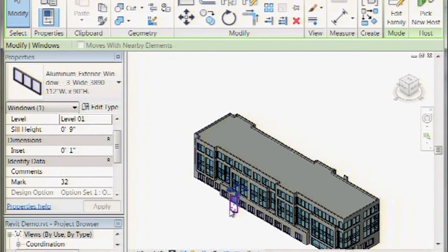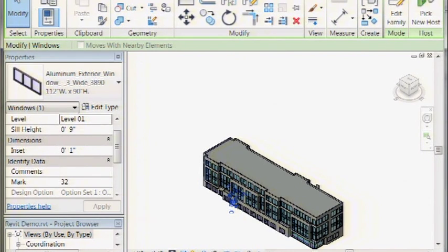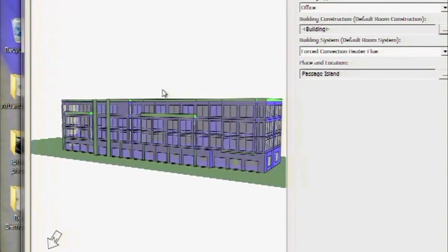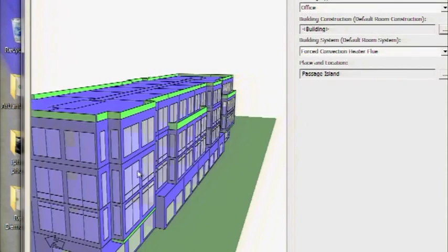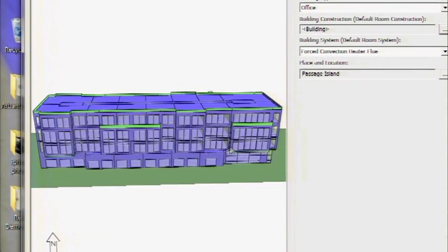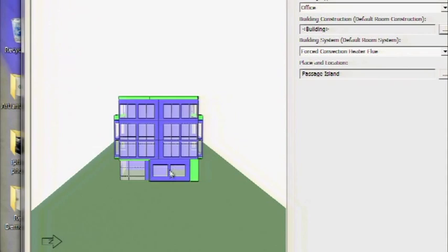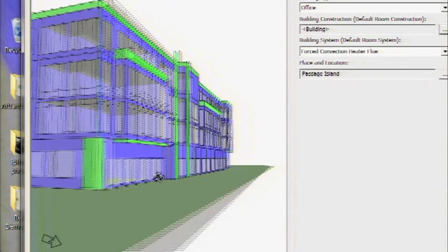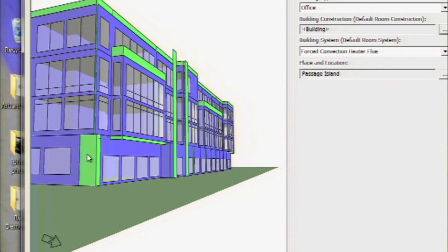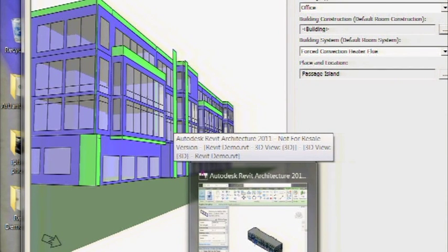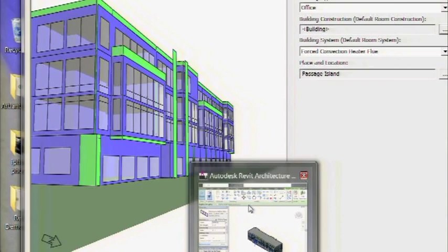You'll also see that a lot of architects will miss a lot of rooms, like that space here on the side. This space is where I had that little jog coming in, and that was not defined as a room. It could just be a mechanical shaft or whatever. A lot of architects also build their columns like this by showing a bump out in the wall. And those need to be treated either as non-room bounding, or there needs to be a space put in it as an unoccupied space. So you can really decide which way you want to handle it.